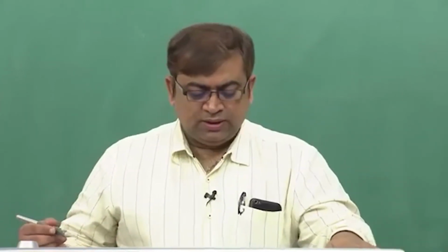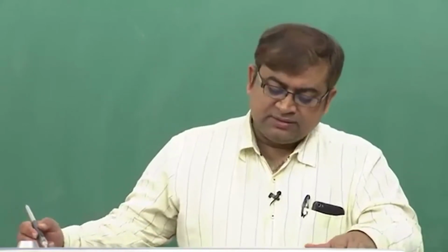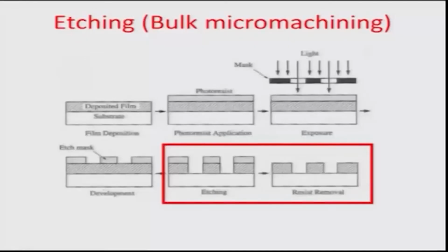So that is how you do negative tone photoresists and lithography. What is the next step? It is actually about the etching process. Supposing we had developed a photoresist layer and a mask, which is a sacrificial mask or an etch mask, over this layer which is hatched, and it is probably something which is to be attacked by a chemical or an acid.